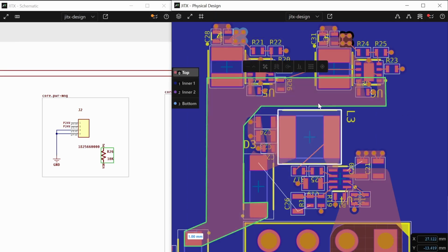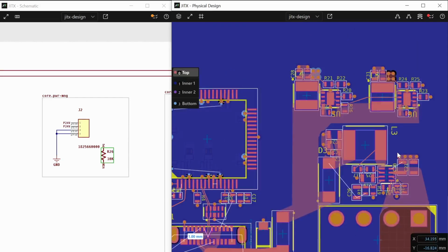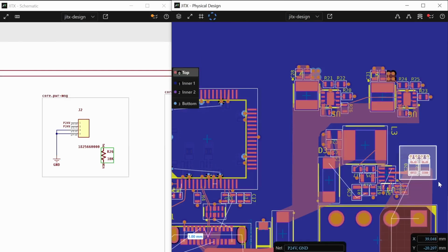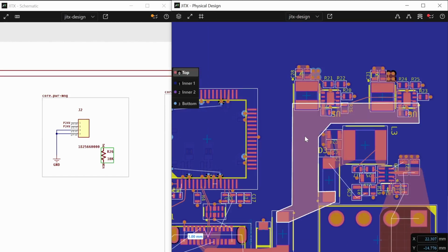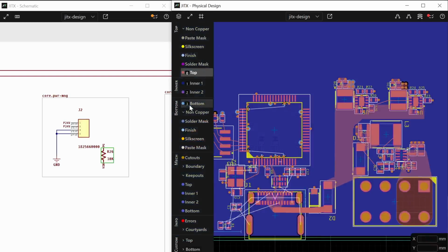One thing to note about this pour is that once it's edited, it no longer updates live. So these we haven't edited and it's just auto-generated. The new shape can be calculated automatically. Once you edit a pour, it is no longer auto-updating. So just one thing to be aware of there. Let me show you one more method of creating power pours to finish up.